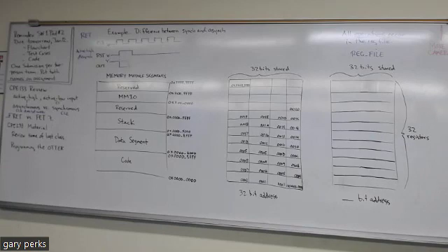When you add 1 to something, that addition is going to happen in the reg file. If you do any sort of logical operation, you'll see when you look more closely at the instructions in the ISA for the otter, there's instructions where you can AND contents of registers together. You can OR contents of registers together. You can do all kinds of logical operations. They all occur in the reg file. So all operations occur in this reg file. And again, there's 32 registers and they all can hold 32 bits.